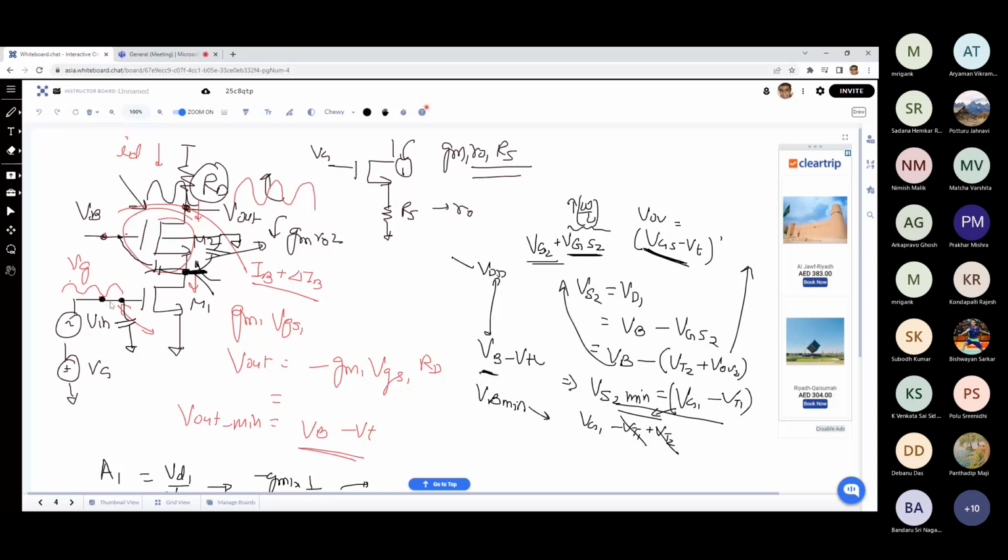So in the earlier design, the dominant capacitance, at least we are sure, would be CGS of M1 because of the Miller capacitance, and it will definitely create a dominant pole, provided the input itself is coming from a stage which has sufficient output resistance, comparable to RD, basically a few kilo ohms of impedance. Then this will become dominant. Is that clear?